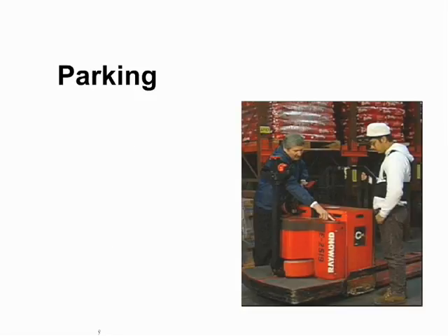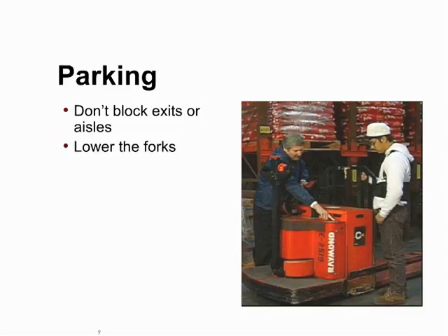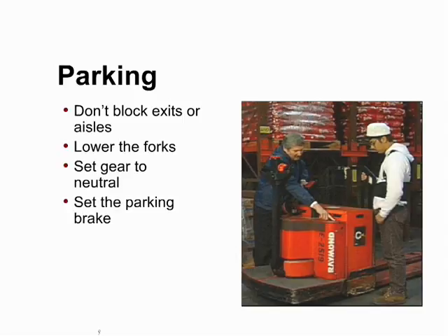When parking a forklift, remember these safety rules. Don't park in a way that blocks an exit or access to emergency equipment. Lower the forks to the ground so that no one can get under the forks. Set the gear shift to neutral. Always set the parking brake, and turn off the key.